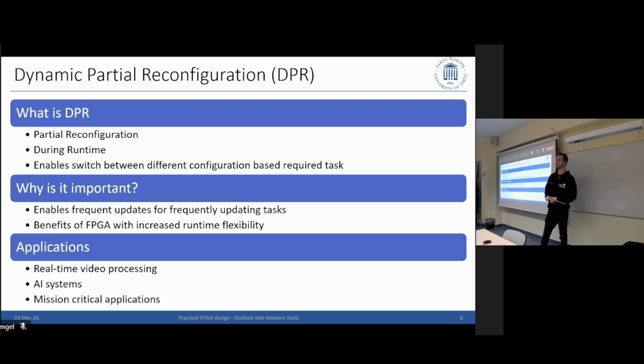So you can have your FPGA still running with whatever accelerator you want. Maybe I have a neural network accelerator and I want to run a different neural network, right? Or I need a different video encoding or signal encoding or whatever, switched during runtime. Then I can just switch part of the logic and reprogram only that part. And then I still have the rest running, and then I can switch to the other accelerator and reconfigure the rest or whatever. And I never have a downtime, which of course can be quite nice.